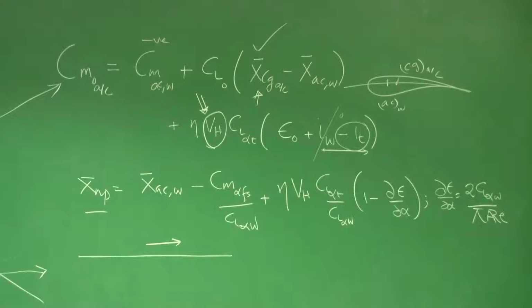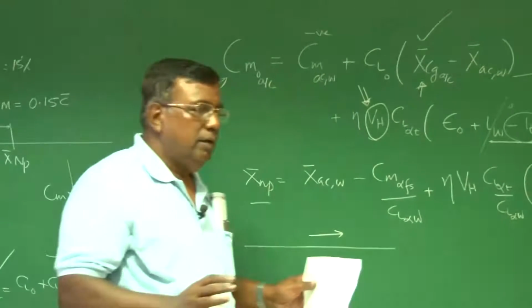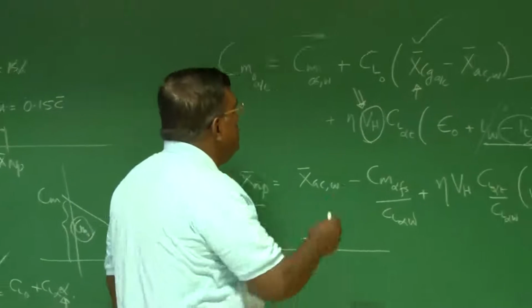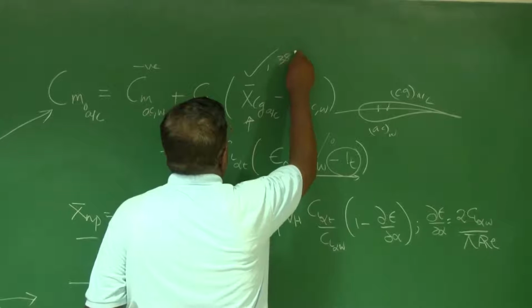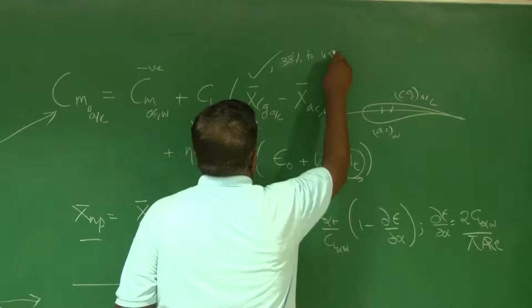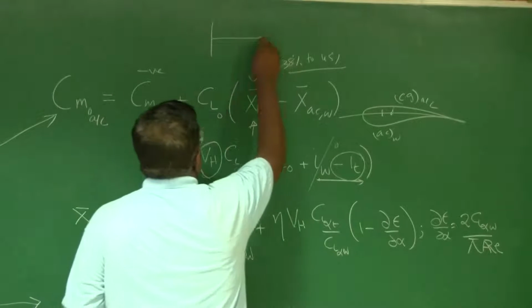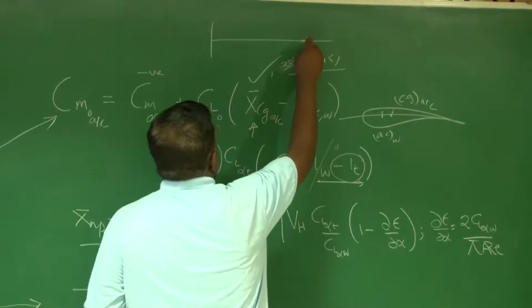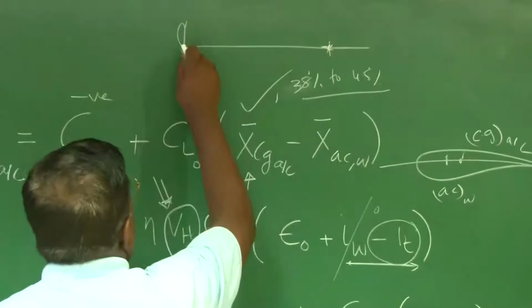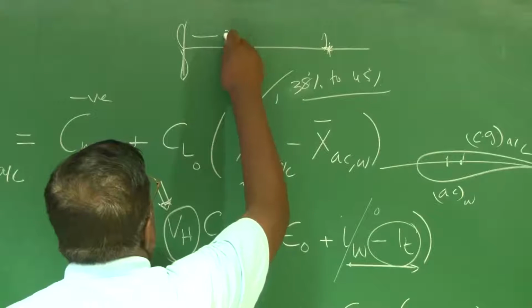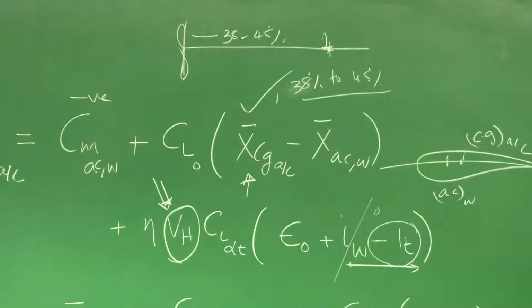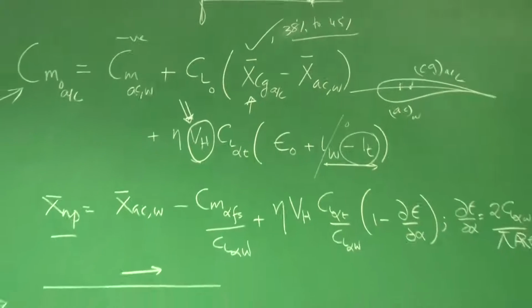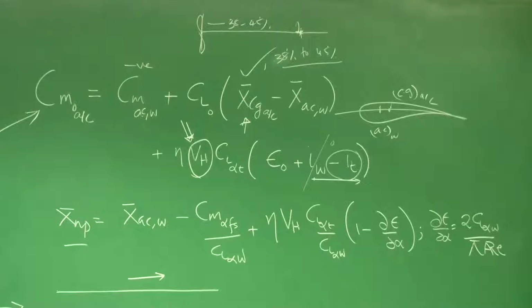So again, we take advantage of historical data, and we know this will be between 38% and 45% or so, from the leading edge or from the propeller here. This distance, you will find, roughly 38 to 45% of the total length will be the CG. These are numbers, right? And a good designer will see from different configurations where exactly the CG is located.